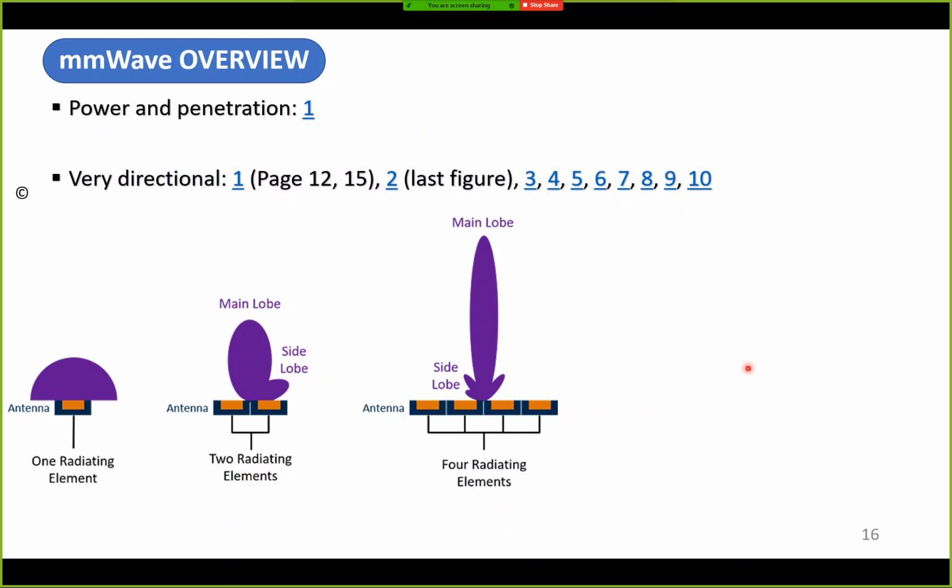As a remedy to these disadvantages, 5G signals will be very directional in contrast to 4G. That is, these 5G millimeter wave signals will be very directional. So if we assume all these signals are millimeter wave signals, as you see, if we can make this signal more directed, if we can compact the energy in the main lobe, we can reach further distances by having directional beams. And we can have these focused signals by having more antennas. As I mentioned, we can pack more antennas at higher frequencies.